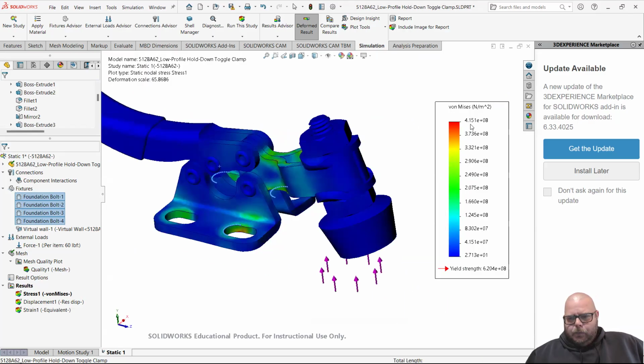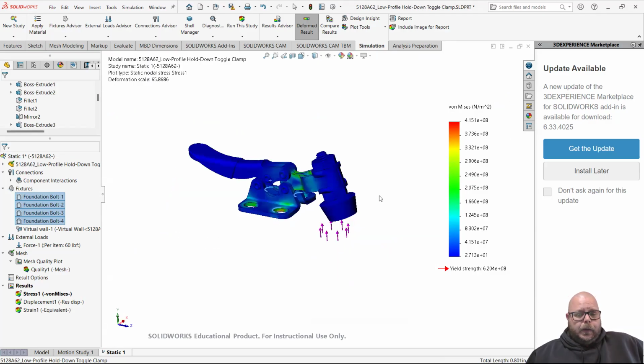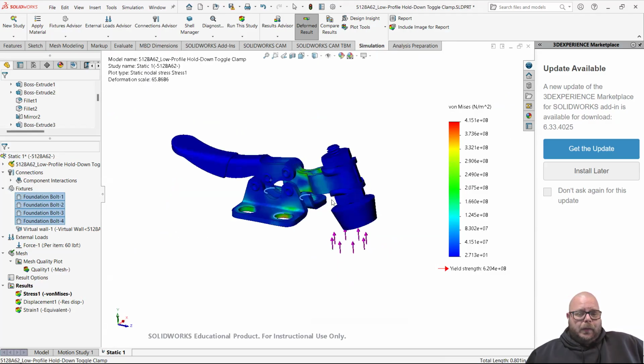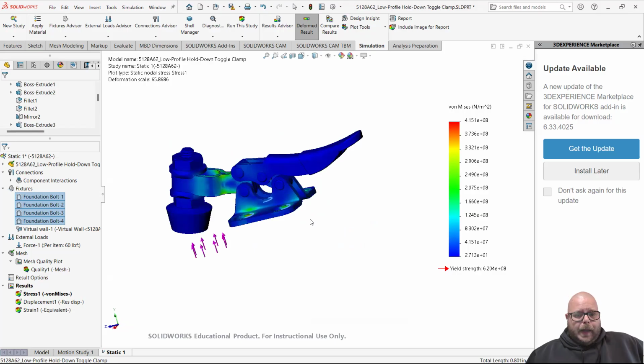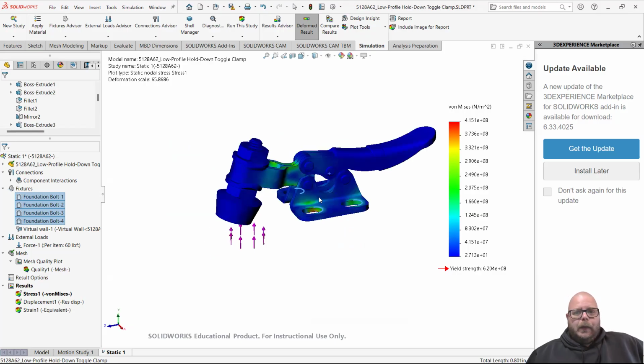Quick check on stress, right? 0.8 here, 0.8 here. We're in the same order of magnitude. We're about 2/3 of the yield strength. So we're getting up there. We don't have much of this. We don't really have a safety factor anymore. We're getting close to yield at 60 pounds, which, as a first pass, again, as a single part, all steel, I would buy that. And I would buy McMaster's verdict that this thing is maxed out at 60 pounds.